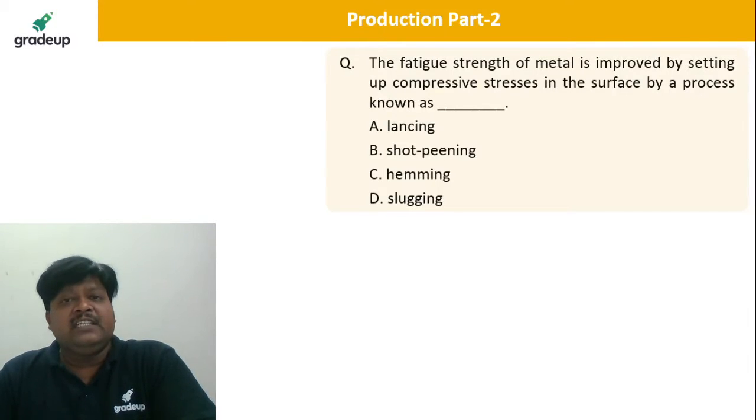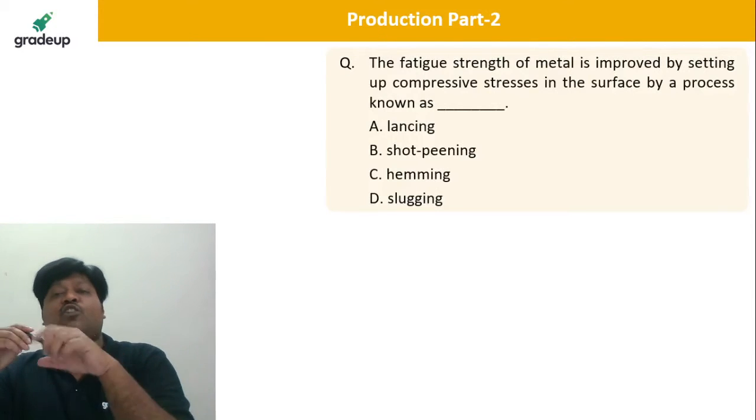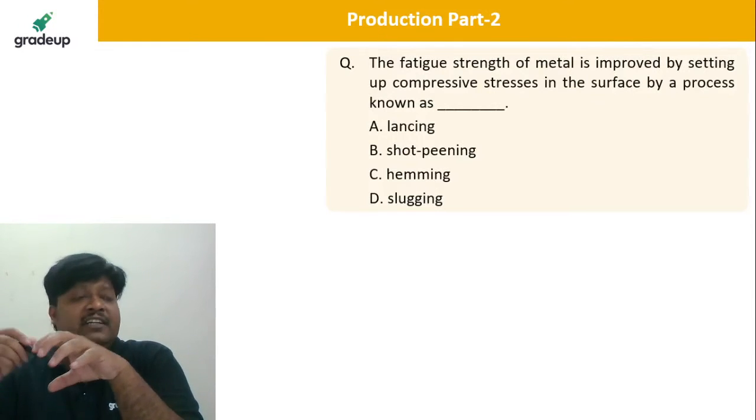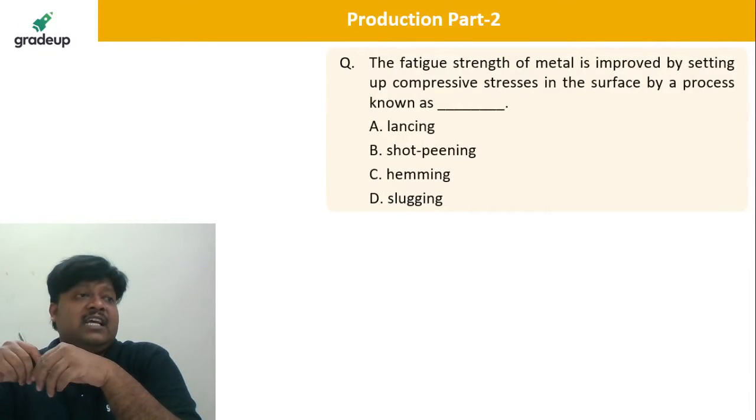Yes, to increase the fatigue strength of the metal, dear students, what are we going to have? We are going to have shot peening. With shot peening we are trying to produce compressive stresses on the surface. Yes, that is correct.